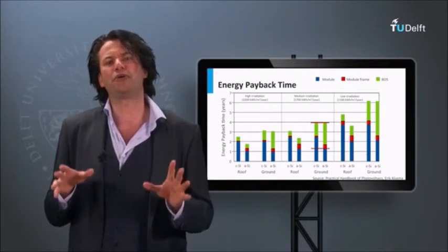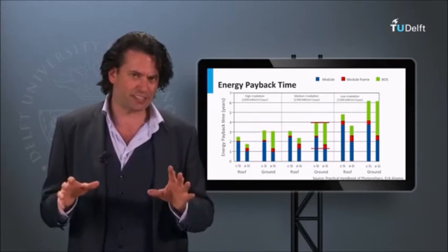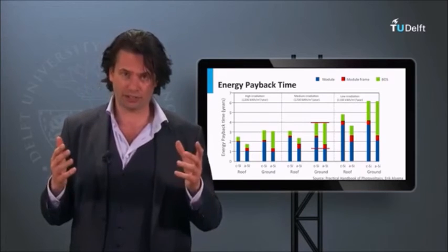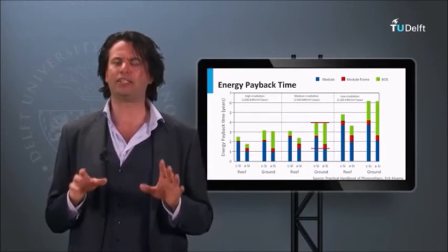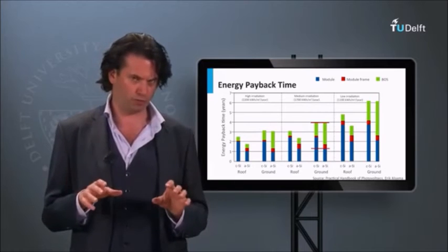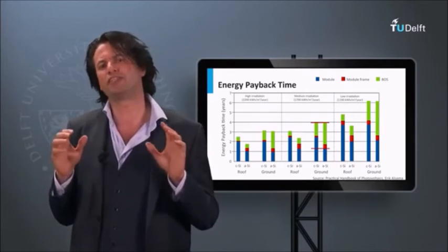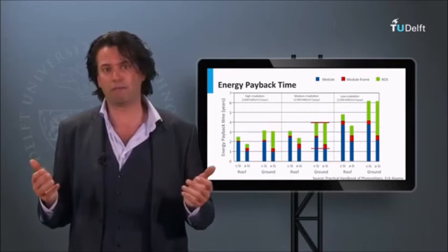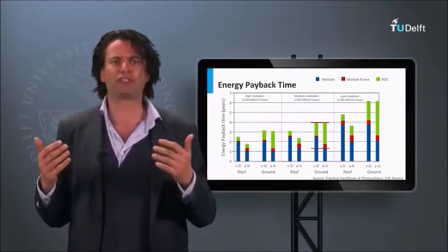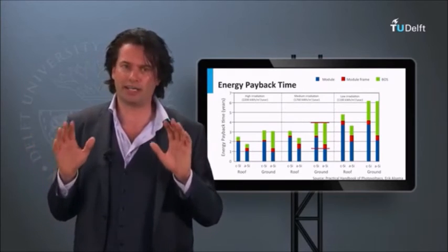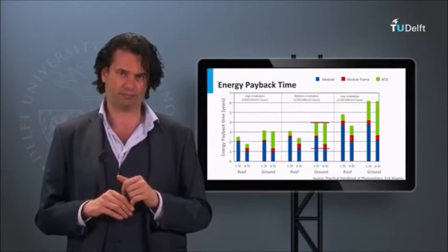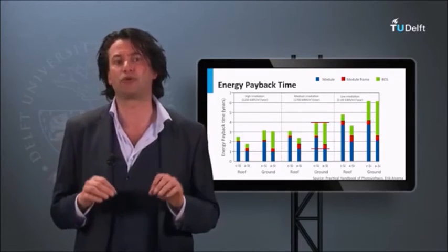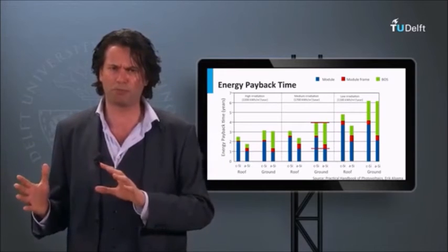I would like to remind you again that these fascinating differences in PV technologies can also affect the design choices at the system level, just like we had seen in week 7 in the modules block. The thin film amorphous silicon panels can work better under diffuse light. The crystalline silicon panels are more efficient, but amorphous silicon panels are less power intensive while manufacturing. So we see again that a lot of optimization is required at the system level to choose the optimal module depending on several factors.